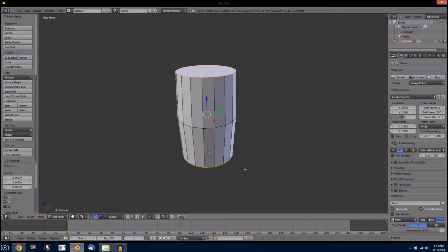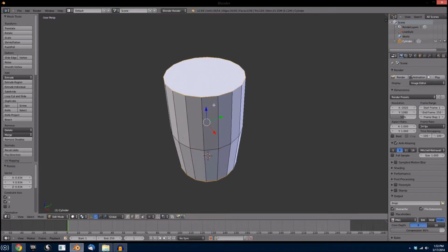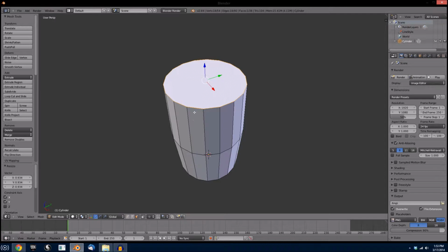I really don't want to go into a whole lot of detail because you make this video super, super long and boring. One thing that I do want to show you how to do is on many, many other Blender tutorials, but if you just didn't happen to catch one of those, I'd like you to see it on this one. We're going to make the indentation in the top of the lid. In order to do that, you go into face select mode and select the top face of the barrel. We move the mouse outside, hold Control and hit F.